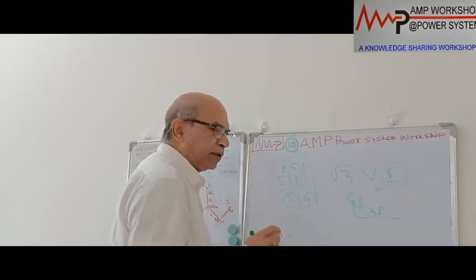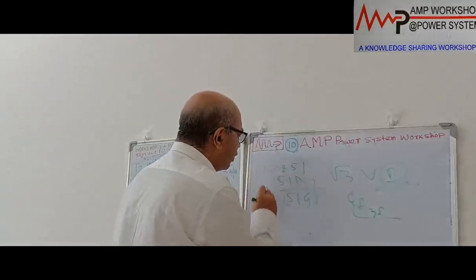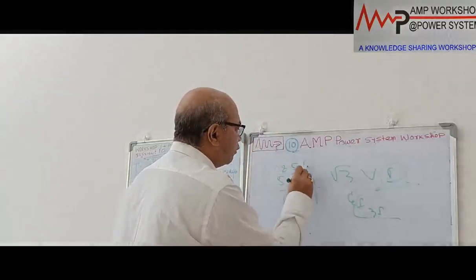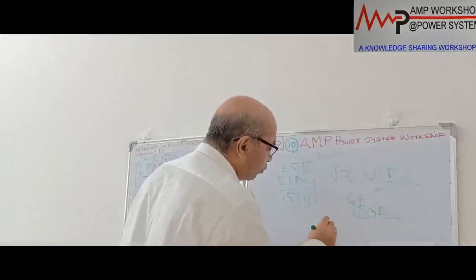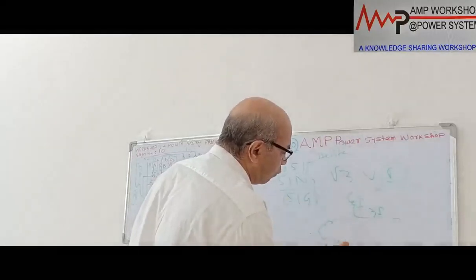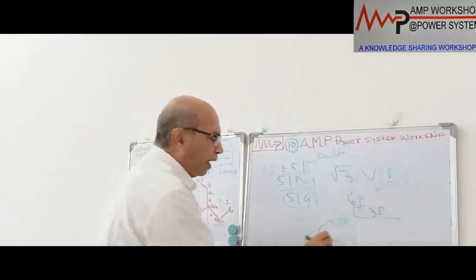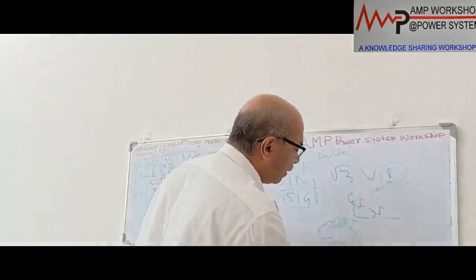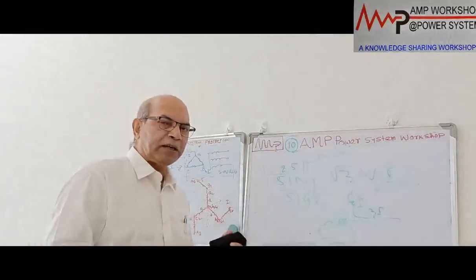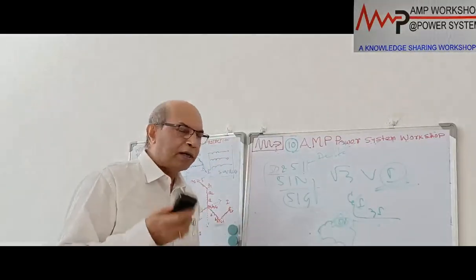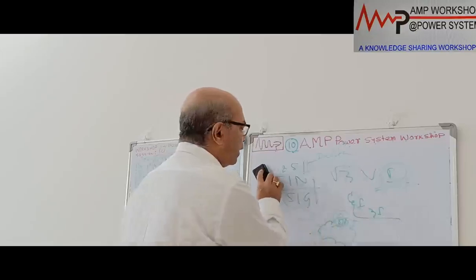In addition to this, for external earth fault detection, the peculiarity of this is that the phase fault CT set will be connected in delta, not in star, and on that closed delta part we put a 51N relay for the external earth fault detection, and the phase 50 and 51 will be connected over here. That is the protection about this, and the capacity calculation of the earthing transformer is 1/10 of the kVA capacity of the transformer based on the fault current and the line voltage.